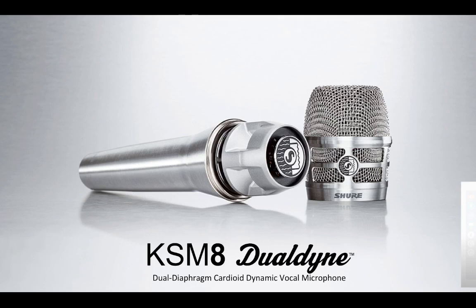So the proximity effect, we'll talk deeply about what that is, but it's basically the buildup of bass response as you get closer to a directional mic of any type, whether condenser, ribbon, or dynamic. As you get right on the grill of a dynamic or directional microphone, it gets muddy and warm. You get a couple inches off and it might sound nice and balanced, and then you get too far off and it's kind of thin sounding and you're fighting to get more low end out of the microphone. That's called proximity effect. It's physics. There's no real way around it, kind of until now.